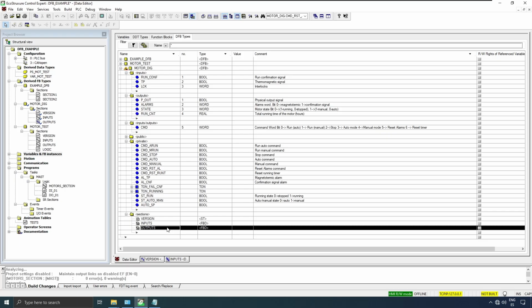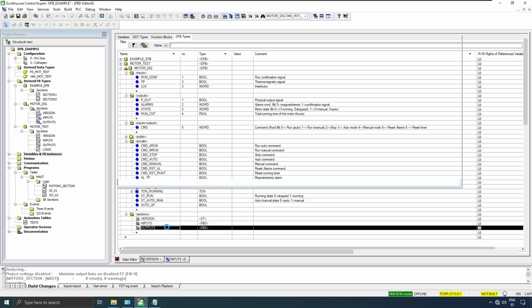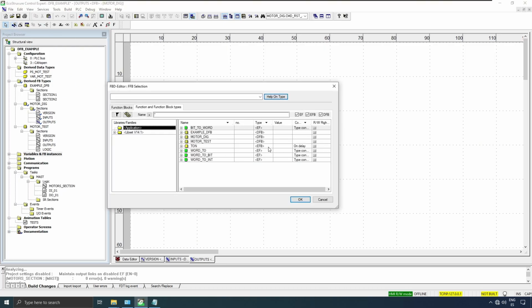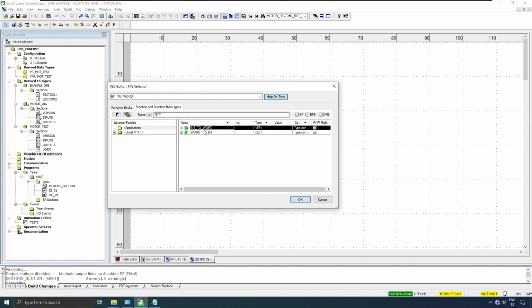If before we unpacked, now our objective is to pack. We are going to collect all those status and fault signals scattered throughout our code and group them into ordered registers to send them to the SCADA in the most efficient way possible. To do this, we will insert the inverse block to the one we used previously. In this case, we will need 2 instances of this block.